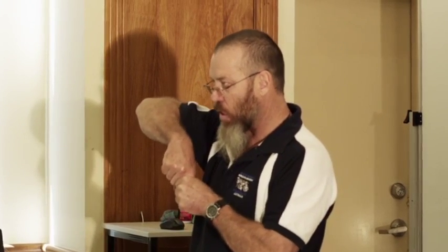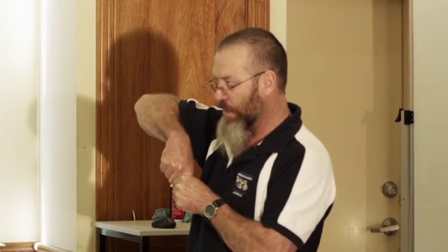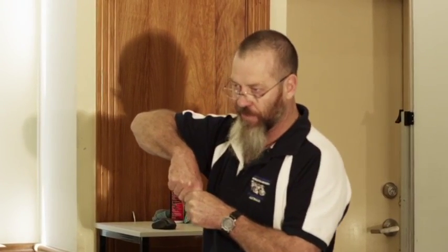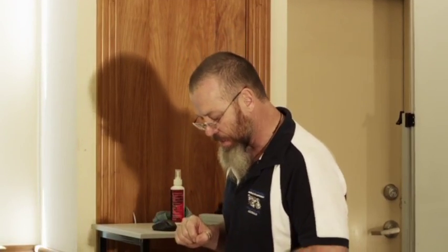So the ironbark has a very, very high ability to hold that fixing. Therefore, you don't need as strong a fixing. You might, instead of using a deformed shank nail, a twist shank nail or something like that, you'll only need a plain shank nail. So that's why we need to know about joint groups. And then we go and select the tie-down connection.